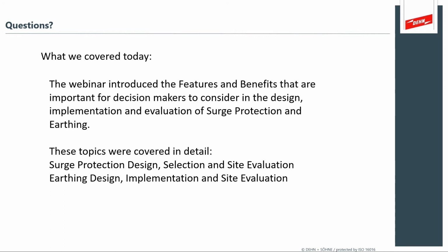The NFPA and UL methods, although they're very thorough, they don't have some of the same testing of direct strike lightning energy on SPD devices. So the risk assessment will tell you the measures you need to put in place, and that helps you pick the surge protection device and the energy it needs to withstand.